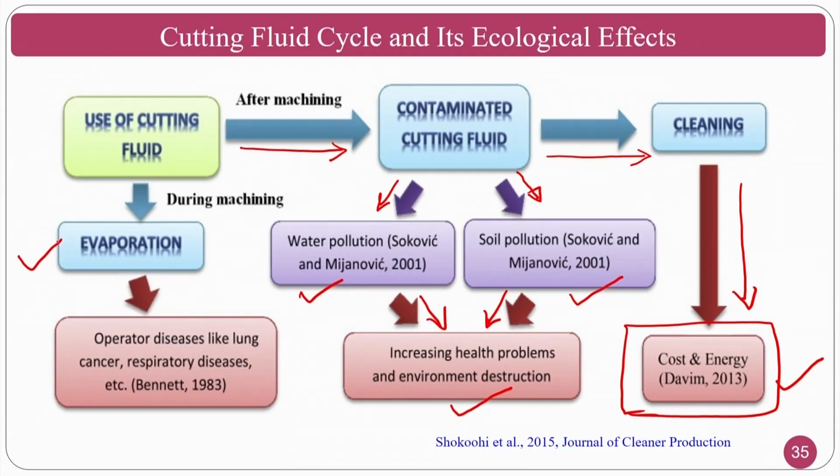Otherwise, you can go for evaporation, like mist cooling or minimum quantity lubrication. But this also causes problems like lung cancer, respiratory diseases and other things. We have seen that cutting fluids have their own positives. Anti-rusting additives protect from rusting, and biocides protect from the growth of biological organisms like fungus and bacteria.